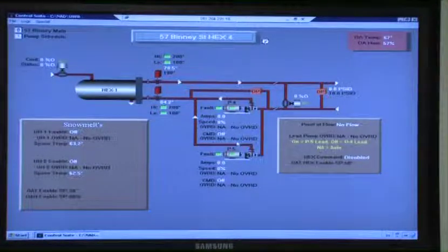Can I ask you this? If this is here, set point, heat exchange enabled at set point 50. Mhm. So it's telling me right now it's not enabled. Right. It's not going to work because it's 67 out. Right. Does that mean everything's like I see here? Nothing runs. Pumps, there's... Yes.